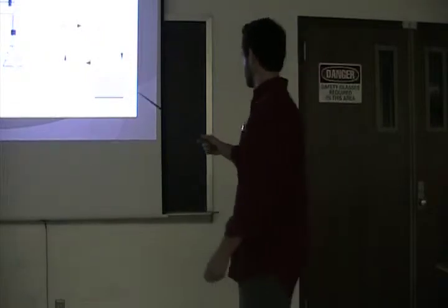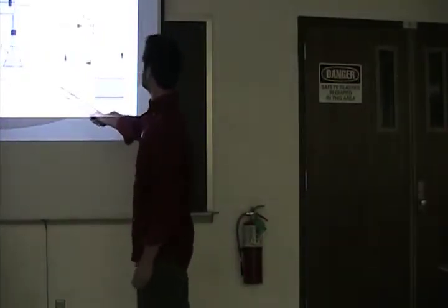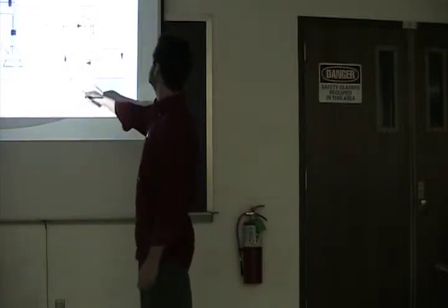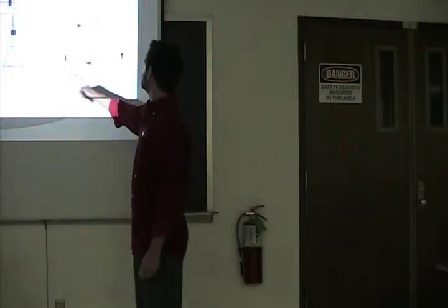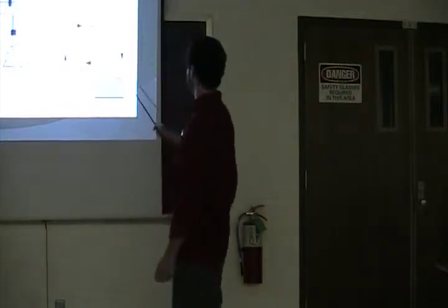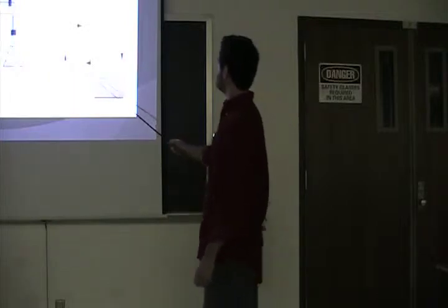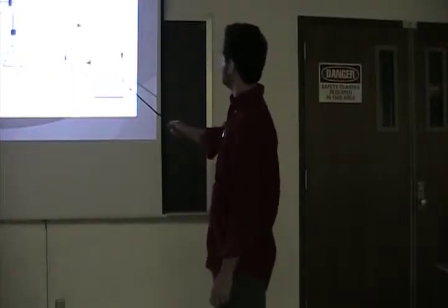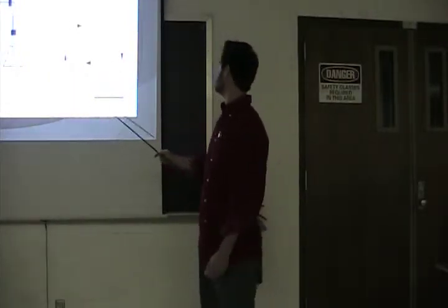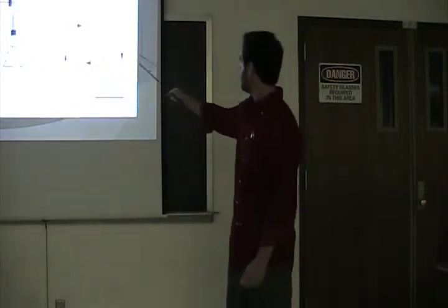And this is our apparatus right here. This is our data acquisition. This is our test tube, the heater, pressure transducer, sight gauge, and thermocouple. And this is our vacuum apparatus right here. Basically, it's a Venturi pump. So when we turn on the pump, it's going to pump water through here, and it's going to pull